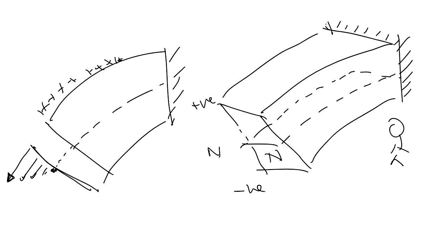Then once I cross the neutral axis, all these arrows will be reflected, on the opposite side. Of course, the change here is uniform, which means that if you draw a line between the first arrow on the tension side and the last arrow on the compressive side, you should end up drawing this shape.